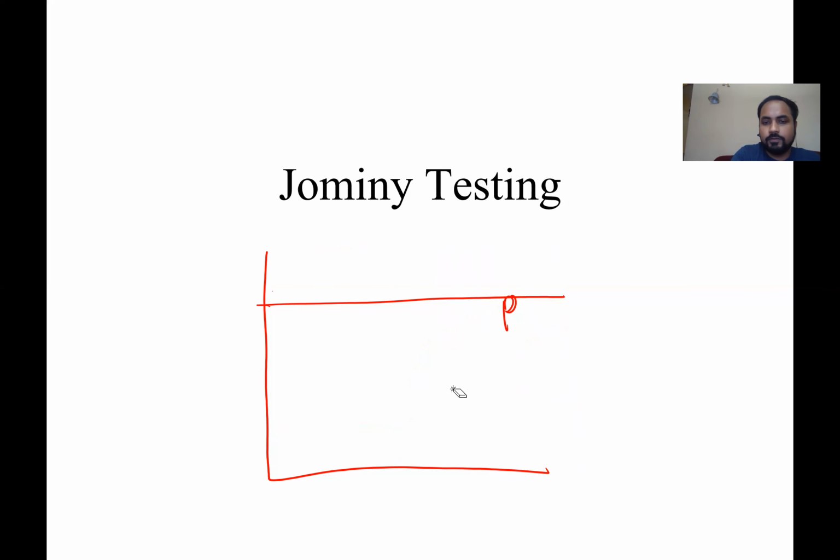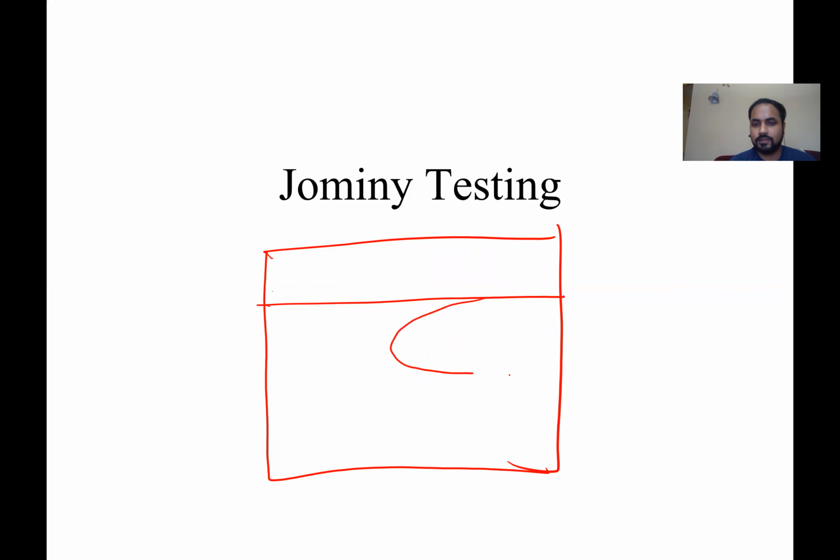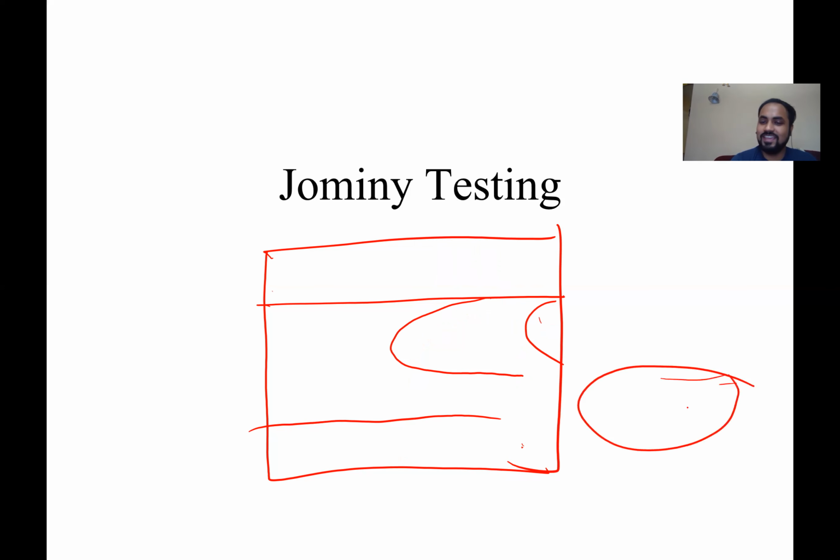So if you want to form bainite, the TTT diagram looks something like this. It gets complicated. TTT diagrams can be super complicated. Then there'll be a discontinuity. Then you have this region here. Now, what happens is bainite will be somewhere here, way on the right side. This is your time axis.